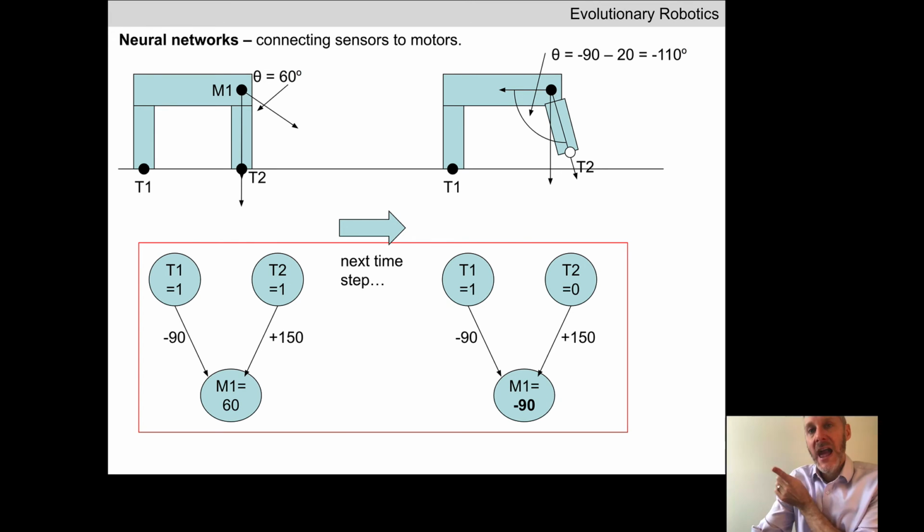We have set a joint axis pointing into the screen, which means in this cartoon, the front leg is rotating in the plane of the screen here. So what we are applying are torques. The motor is trying to twist the link to rotate relative to the torso. So angle is the desired angle. In this example, we're assuming that positive angles mean that the leg rotates counterclockwise in front of the torso, and negative angles mean that it's rotating under the body.